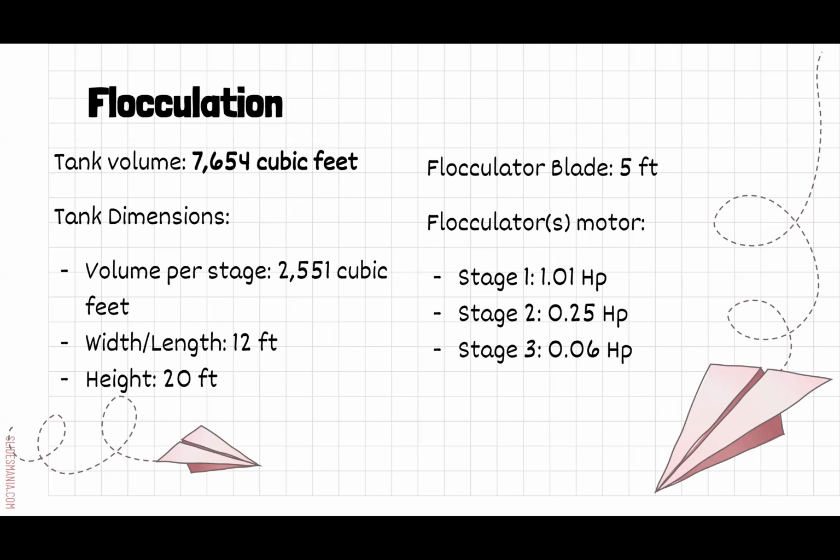Based on that, for our flocculator motors, for stage 1, we got 1.01 horsepower. Stage 2, we got 0.25 horsepower. And for stage 3, we got 0.06 horsepower. And then handing it off to Elizabeth, who will talk about sedimentation.